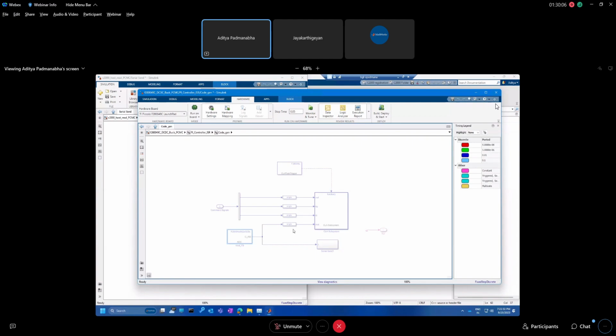You can even increase the sampling of the ADC, oversample it, then use window-based filtering and use that filtered data to run the controller. So out of the ADC, you can use an IIR filter depending upon what kind of noise you want to filter.